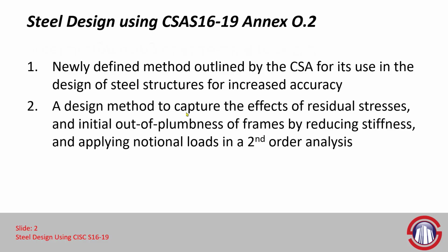It also has the ability to automate the application of lateral forces in the most destabilizing direction, which reduces the number of load combinations you would need to define within S-frame. And this helps you capture the critical demand forces without having to create 4 different load combinations per frame. S-frame will also report the ratio of the second order drifts to the first order drifts for each story, and that helps you better understand the stability effects of your model, and will also automatically add or remove notional load contributions when gravity load combinations meet certain code criteria.